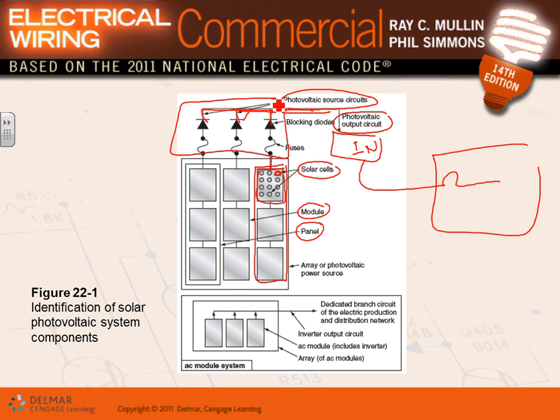This is the DC. This is what they call the DC generation. There's also AC generation, guys, where the panel itself, we have one in the lab right now. If you go to Steve's lab, there's one there, has an inverter. So the AC module has an inverter built into it. And then you synchronize all these inverters, and you get it here as an AC signal. We generate here as a DC signal. On the AC inverter, we generate them as an AC signal. Any comments, guys, about the AC panels or AC modules versus DC modules?